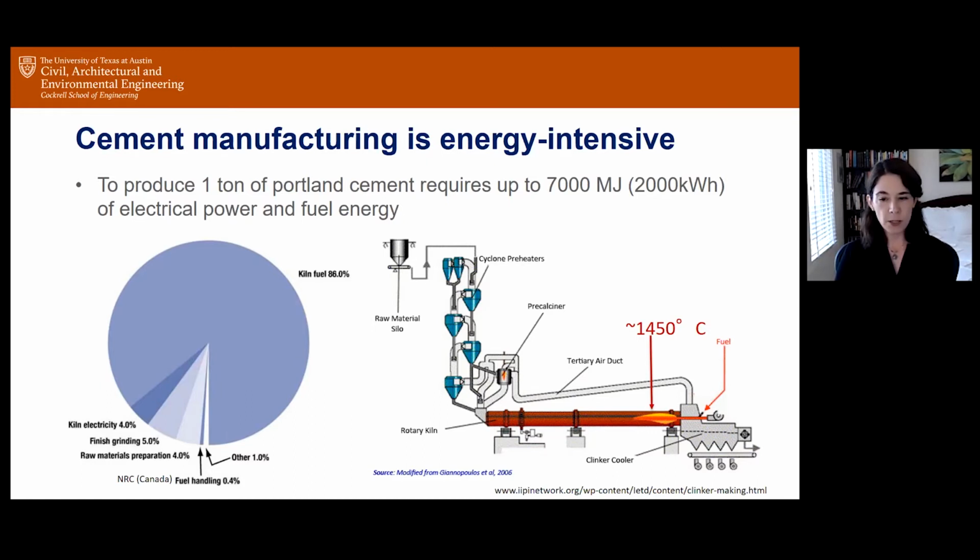So I want to stress that when we're talking about using fuel for the cement industry, we're talking not just about having a high temperature, but that this fuel in some ways gets integrated. The byproducts from this fuel, what's coming off of it in terms of particulate matter, but also volatilized gases, actually combine with the product that you're creating. And so the source of this fuel becomes important when you're considering the quality of the product that comes out. And so that's why I wanted to make sure that I showed a diagram that contained fire.